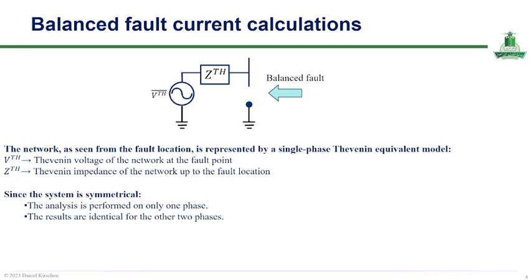Because the system remains perfectly symmetrical during a balanced fault, the analysis only needs to be carried out for one phase. The behavior of the other two phases can be identified from it, which significantly simplifies the calculation process while still providing accurate results for the fault current and system response.